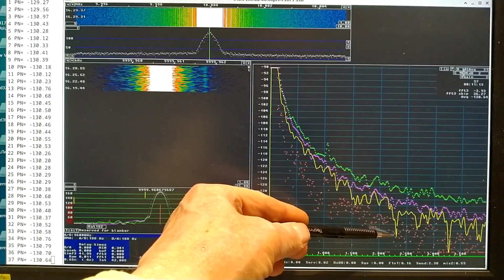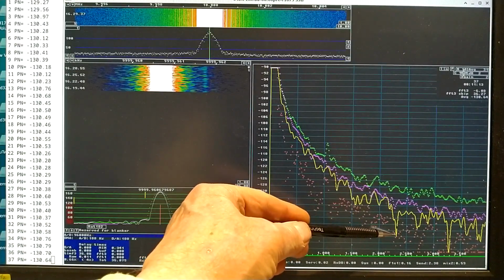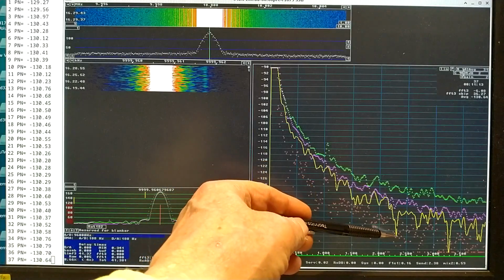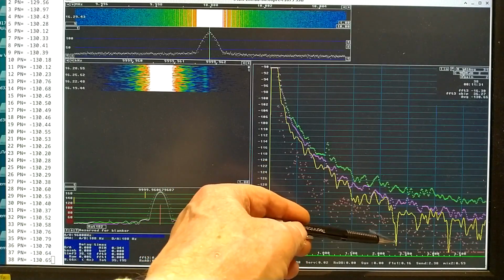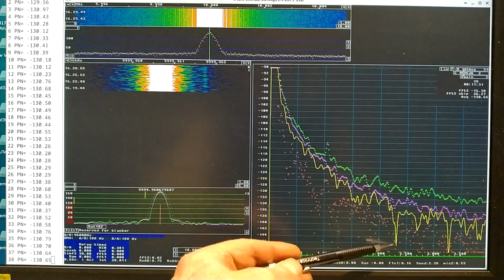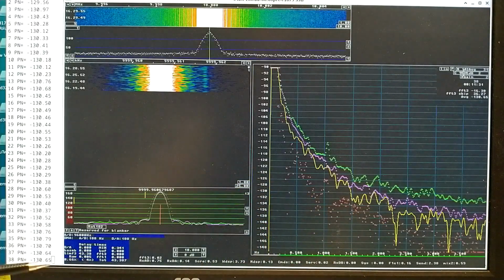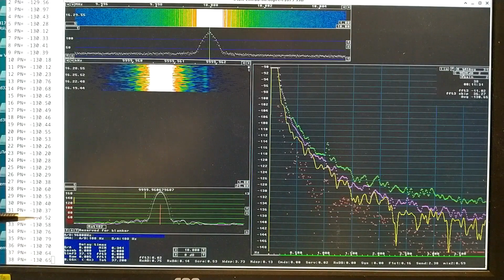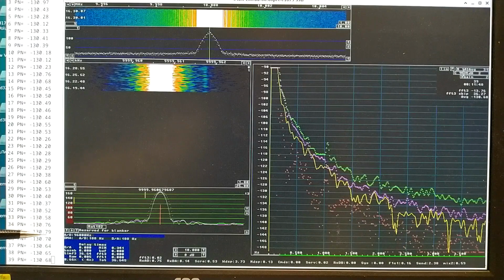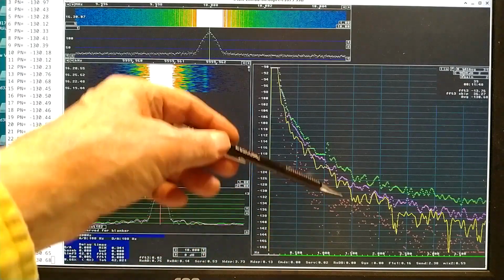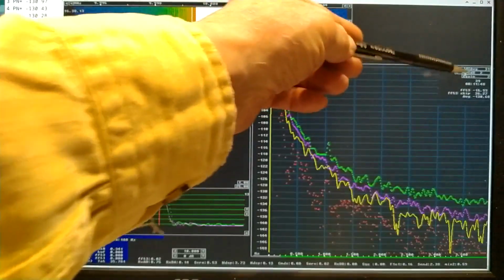This peak was negative a few samples ago, but when it switched from not being counted to being included, I got data points here that are very far from the proper value, and that means that the average will make jumps of a couple of tenths of a decibel, going from 0.50 down all the way, and then 0.8, and now it goes down. So I have to wait a little bit longer than this. This is 11 minutes.